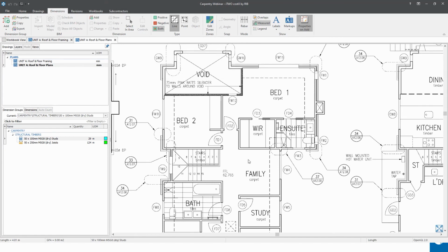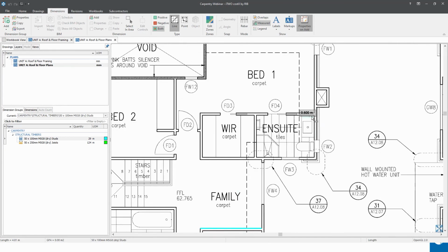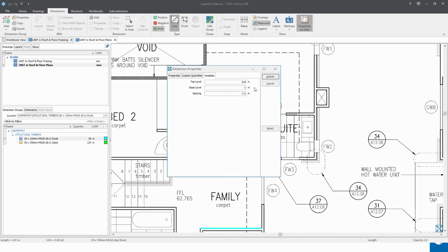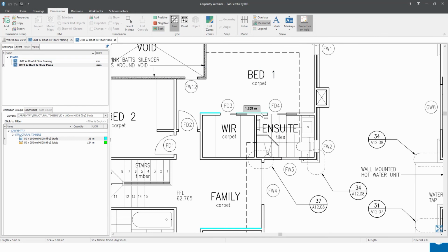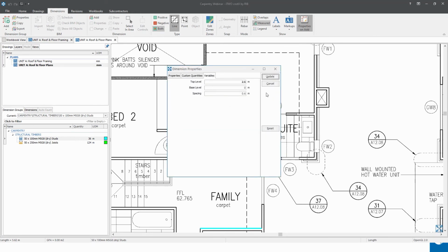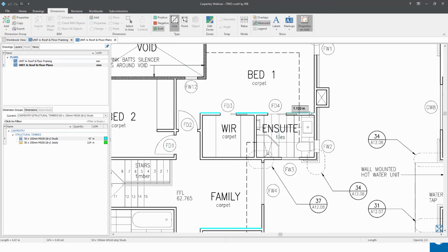And what I'm actually going to do is measure this wall across the walk-in robe and ensuite. So starting at left, I'm first going to measure between the doors, so the full height walls from 0 up to 2.6 are those 3 sections there.